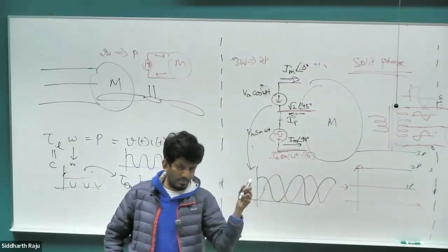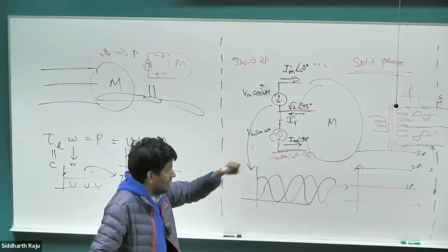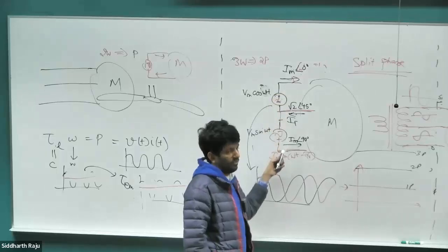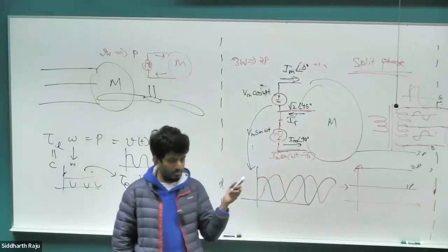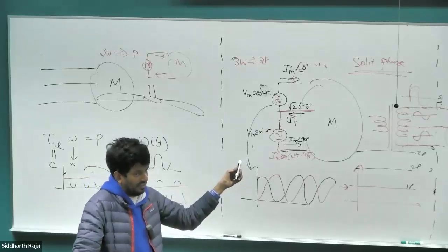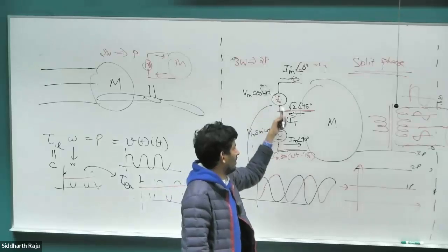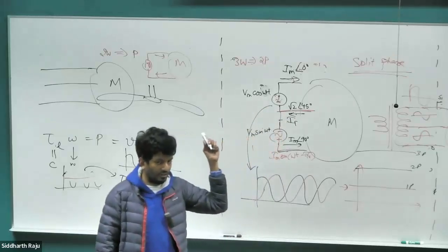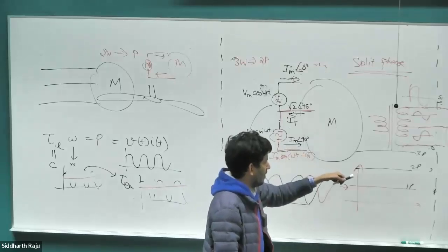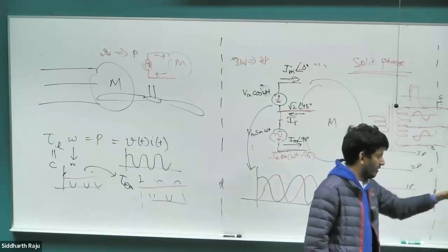So if you had a power system using two-phase instead of three phases, then you would have wires each of them being different from one another, which is very problematic because it increases your cost. When you order in volume and all three wires are exactly the same, you get a significant cost saving compared to two wires being one rating and the third wire being a completely different rating. Right? So economically, it makes sense for multiple reasons to go to three-phase because you have each wire at unity power. In case of two-phase, you get a slightly reduced power.